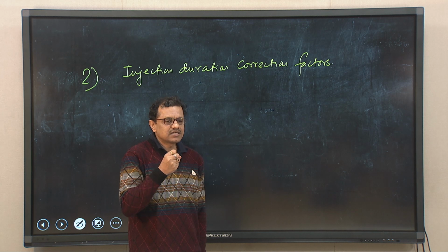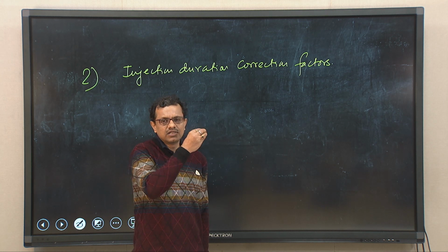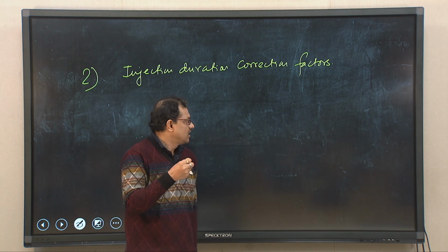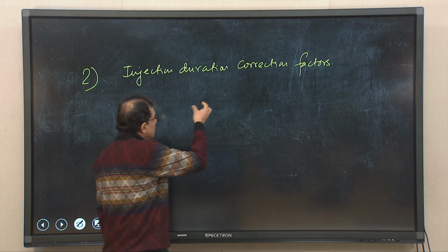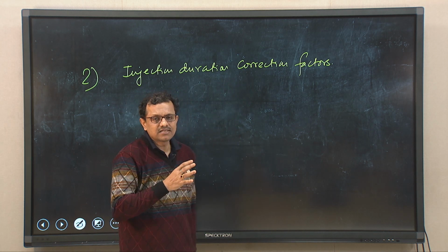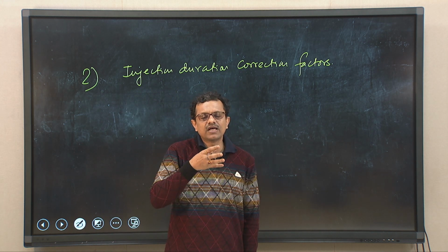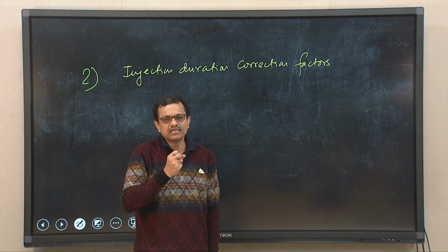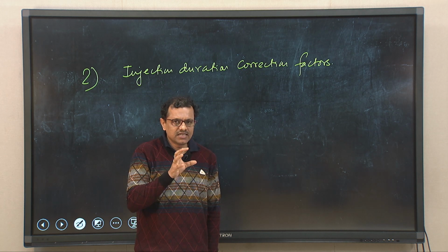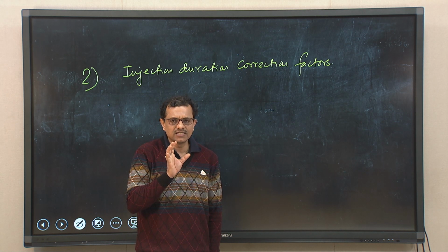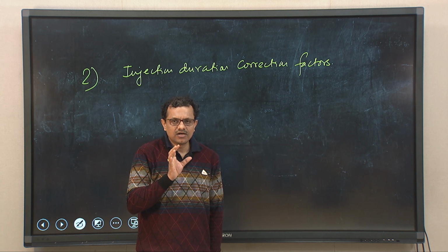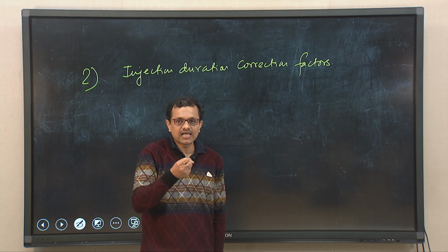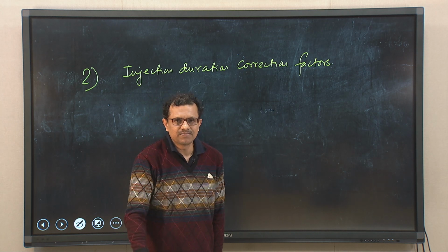All these sensors give input to the ECU, and the ECU, on receiving signals from these sensors, corrects the basic injection duration time so as to comply with the exact requirement of the engine. The basic injection duration is calculated or determined, and this calculation should be corrected to meet the actual requirement, and that is why the second step is necessary.